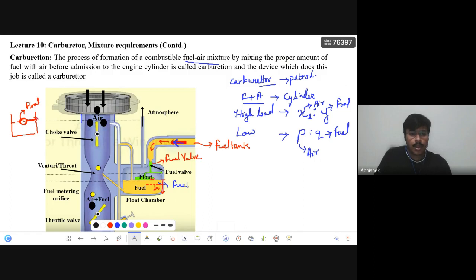and this is a valve, which is connected to the pipe. We always want this much level of water present in the tank. Once the water comes down, the ball also comes down, so the valve will open and the water will come inside. Do you understand? The same thing is done here. As soon as the fuel level comes down, the float valve comes down and allows the fuel to take the place. Okay, so this part is over.